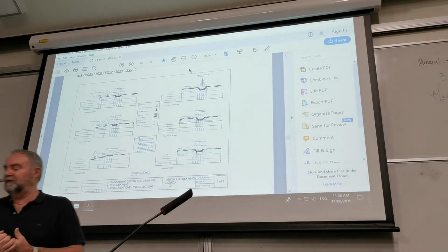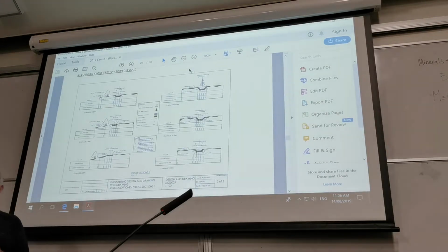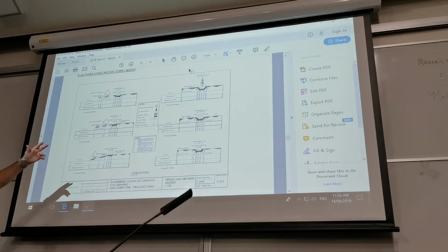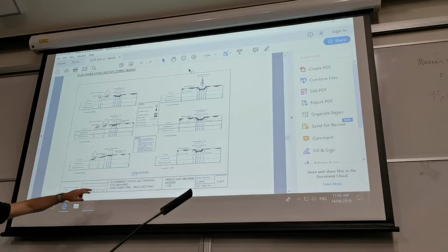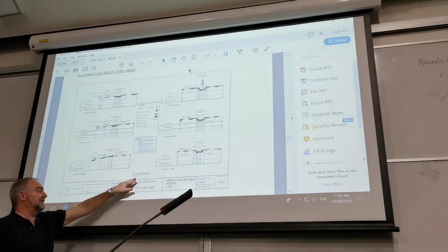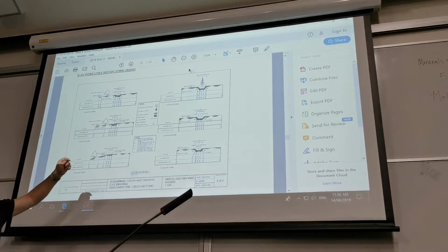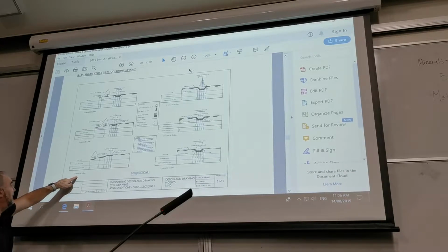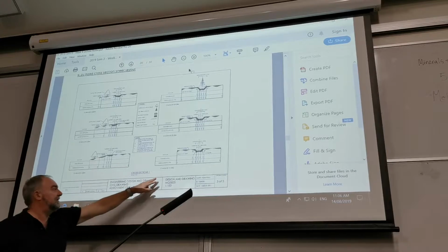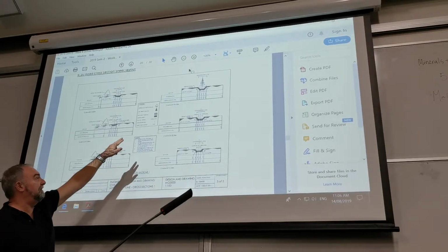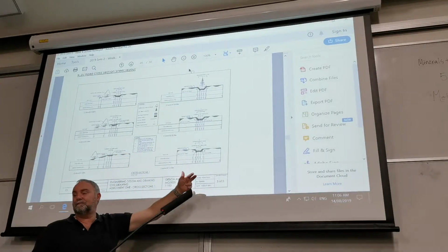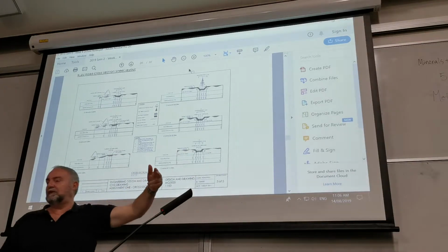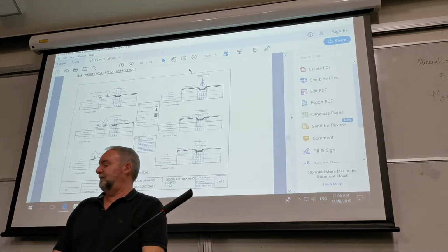How many do we put on a sheet? Well, that is determined by you, basically, the draftsman, the designer. In this case, we got 6 on. That's probably a reasonable amount at a scale of 1 to 100. If it was a scale of 1 to 50, we might only get 4. So as I said, we always go up, so chainage 0, 5, 10, 15, 20, 25, and there was another sheet of these as well. Surveyors would probably do 2 sheets of cross sections, maybe 3.